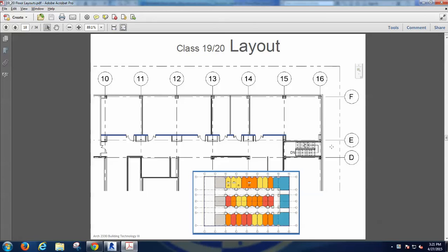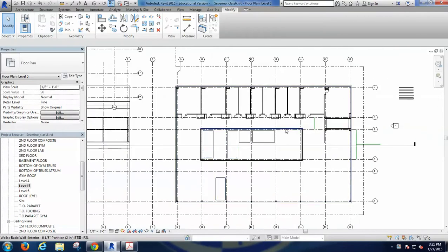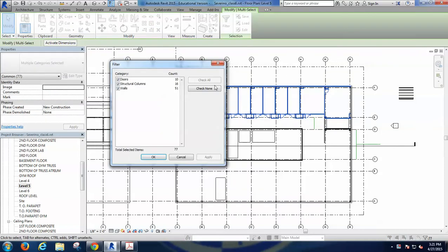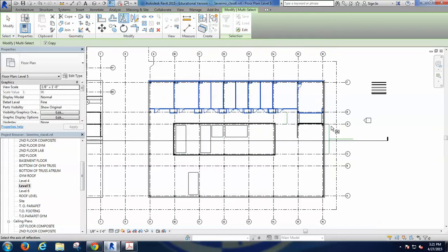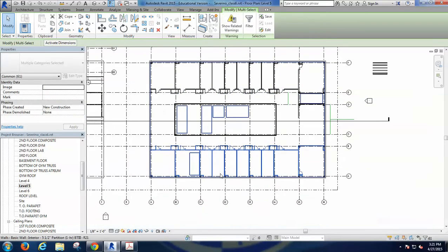I'm going to do that shifting in the stairs so we understand how the shaft should accommodate the stair as much as the stair should accommodate itself to the shaft. Okay, so first of all, I'm going to do a little bit of mirroring. You could select all these elements here, filter out everything but the walls and the doors, and do the mirror, picking an axis. I calculated the midpoint here, so all that would come down automatically.